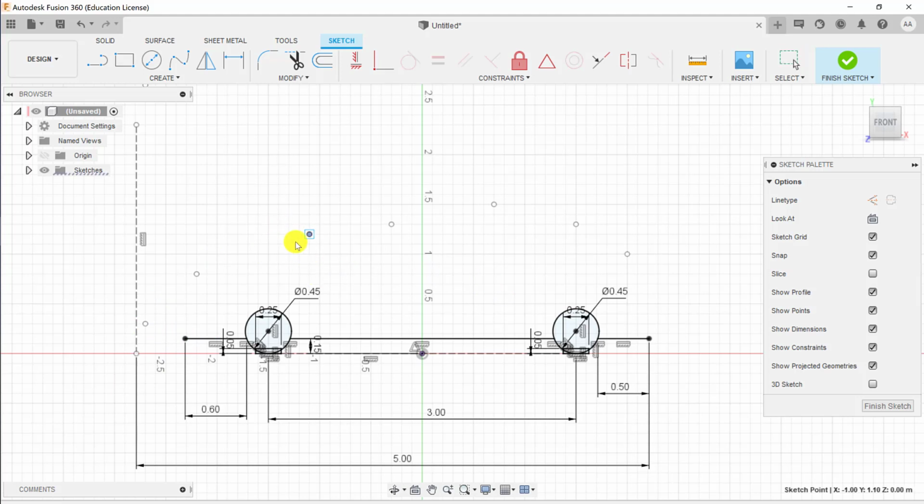Now, these points are just kind of floating in free space right now. We can move them around, and that's not exactly what we want. We want to constrain them so that we define the curve of the vehicle properly. So I'm going to start constraining them individually. This point is going to be the forwardmost point of our vehicle, so I'm going to have it be coincident with this line that we defined earlier. I'm going to give it a height of around 0.25 meters from the bottom of the vehicle. And then I'm going to define this point over here to be another 0.3 meters above that point.